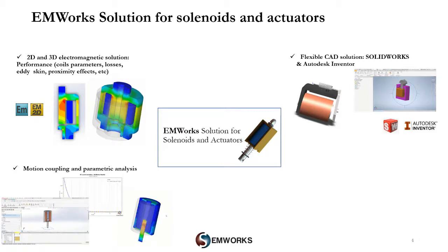Once you couple your EMS study to SolidWorks Motion, EMS internally communicates with SolidWorks Motion to exchange the needed information like position, force, and more. At the end, EMS generates electromechanical results, including the position of your moving parts, the speed, the force, etc. Besides the motion coupling, parametric studies can be performed as well to cover the different design scenarios, like computing the force versus air gap distance, angle, input current, materials, and many other variables. We may use SolidWorks distance and angle mates, sketch dimensions, and more inputs as design variables.